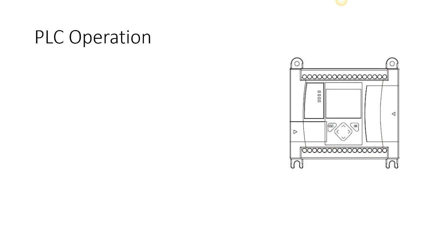Okay, so let's talk about the operation of the PLC. The very first thing that it's going to do is read each input channel, starting at the very first input channel. That is I/0. That's not the letter O, it's I/0, which means input 0. We're going to have a lesson next on addressing, but PLCs are what we call zero indexed, meaning when you start counting, you count from 0, then you go 1, 2, 3, 4, 5.